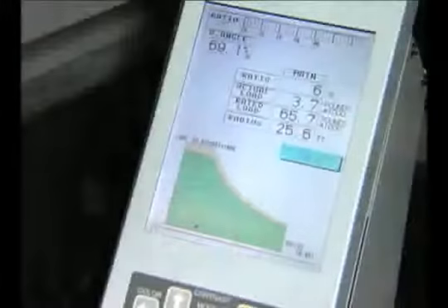The plus sign shows current point of the load block or ball. The yellow area on top shows moment ratio of 90% or more. The next screen indicates the working area that is now permissible in the present crane configuration. The next screen will show the load record of the significant lifts that the crane has made, including any lift over 100% ratio. We will now go into the settings screen.